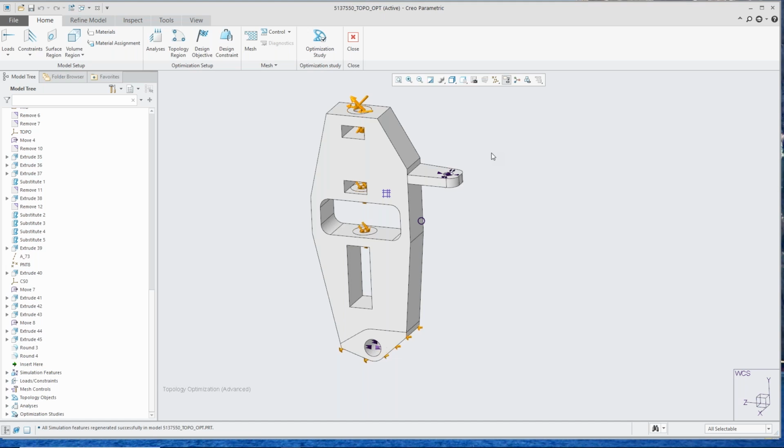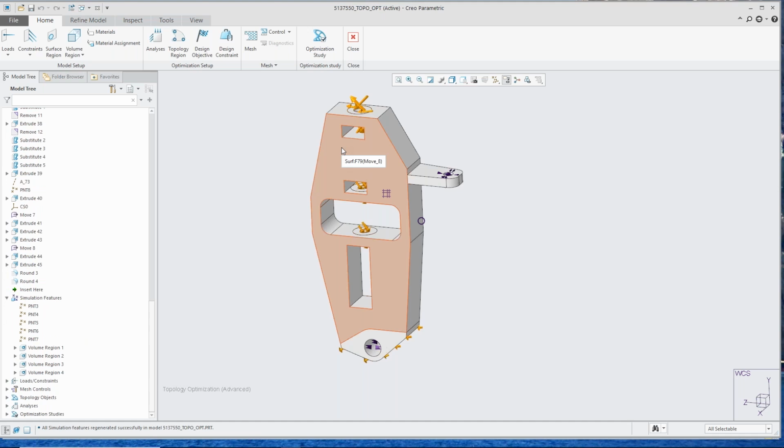And you'll notice it's showing me some different loads and constraints. By removing material, it doesn't just randomly remove material. We have to say, well, there's certain loads, there's certain physical properties that this needs to be able to deal with, right? So it might be constrained this way, it might be loaded that way. So remove as much material and still allow for a deformation of only so much or something like that. So that's kind of how this works.